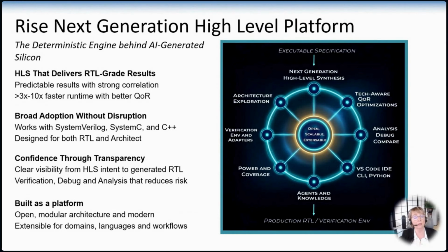So basically you get this loop from your high level executable specification down into your production quality RTL extremely quickly, with a strong correlation and knowledge that what high level synthesis is giving you is actually what you're going to get all the way through your RTL synthesis tool.